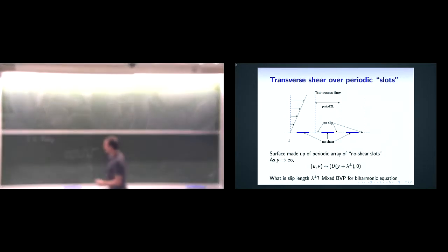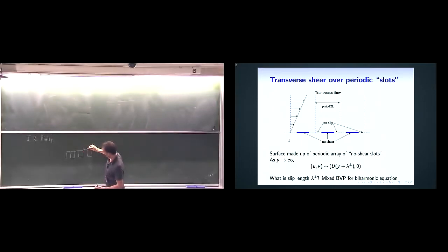And what Philip is assuming is the contact angle is 0. So what it means is they're flat. Okay? And it goes on periodically. So the blue lines here are the blue lines there. The point is, on here, we've got no slip. And on here, we've got no shear. But it can slip. Remember, a free surface can't support any shear stress. A no-slip surface can. It's solid. You know, it's got stronger bonds. Nothing can slip over it, but it can support shear stress. Free surfaces can't. So it's a completely different type. That's why they call these mixed type boundary value problems.